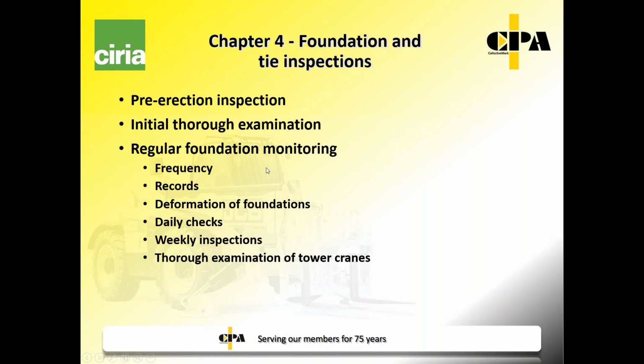And then we go to regular foundation monitoring. It's the frequency, the records. We look at deformation of the foundations. Have they moved at all? Daily checks, weekly inspections, and then there is a bit of advice on the thorough examination of tower cranes. So the point here is that you can't just put the crane up and expect it to carry on without any sort of monitoring. Very important that the foundations are monitored to make sure that they are performing as they are expected to.